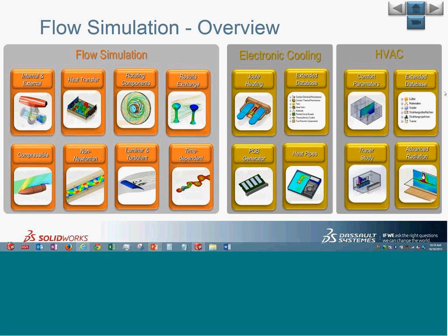And I believe that should help us understand the torque required to resist or create that kind of momentum in the system. In terms of taking the load all the way from flow to motion, I think it would be similar, because ultimately we are taking it to simulation. We can also take loads from simulation to motion. So if necessary, even that can be done. But as that is not required, you can directly do it in flow simulation.